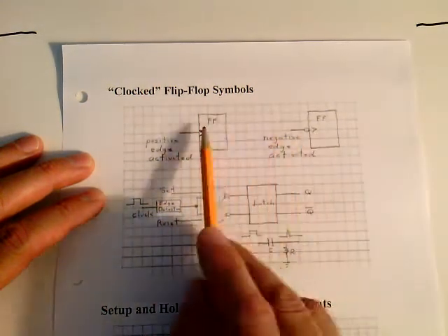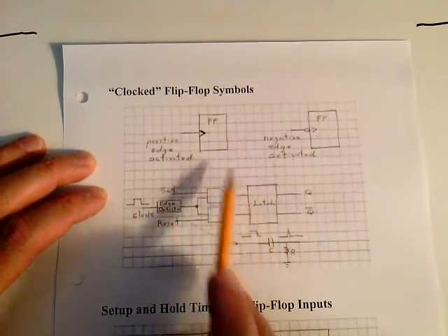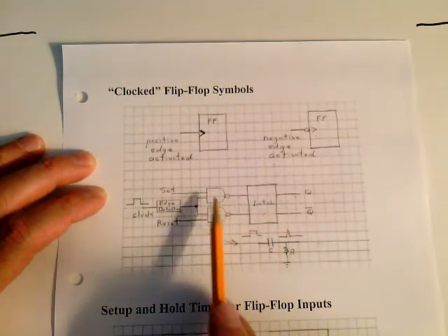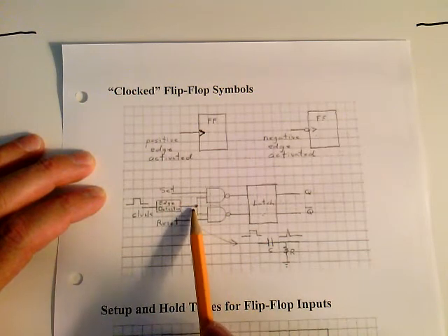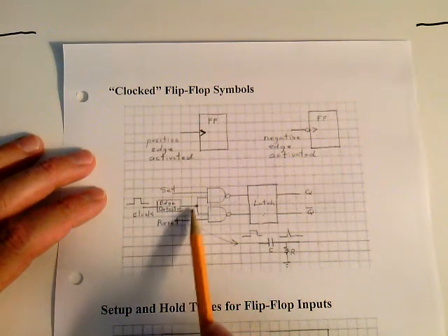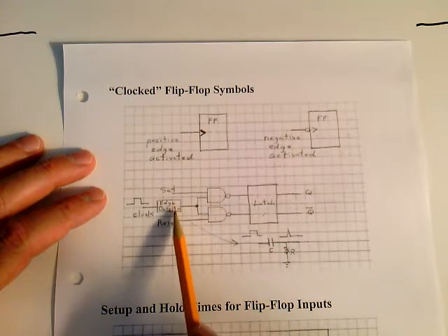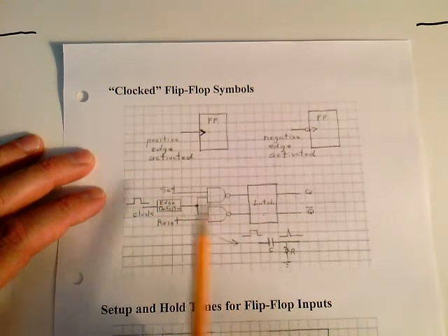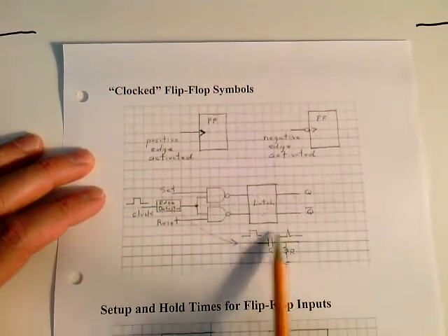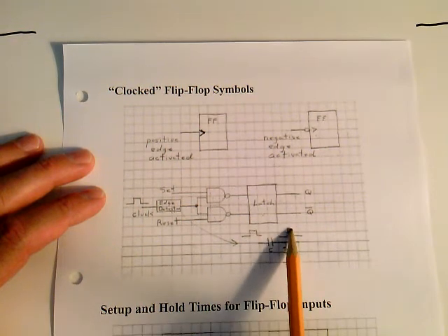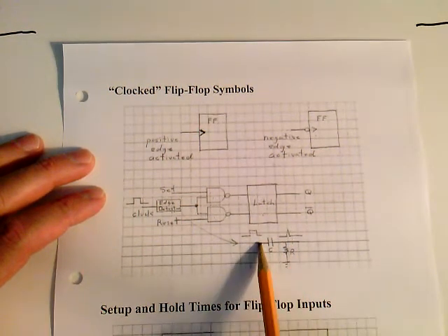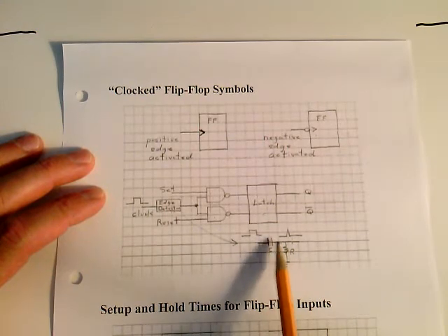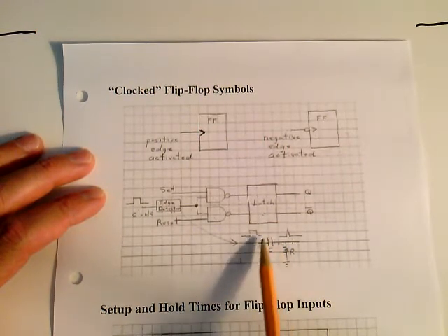So how do they actually do this? Well, if you look down here, we have our latch inside the flip-flop, and we have our steering circuits, and this used to be the enable, but it's not going to be the enable anymore. It's going to come out of an edge detector. This edge detector, we'll talk about what that circuit is next semester. It can be as simple as just a resistor and a capacitor. If you have a pulse coming in, you get an edge on the output because the voltage across that capacitor can't change instantaneously. But that's for another course.